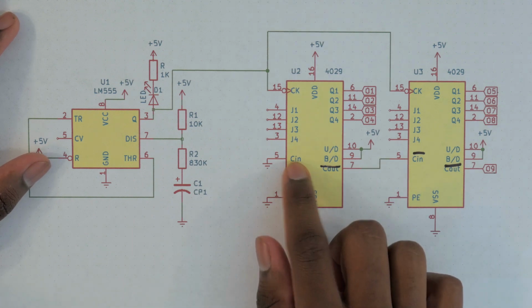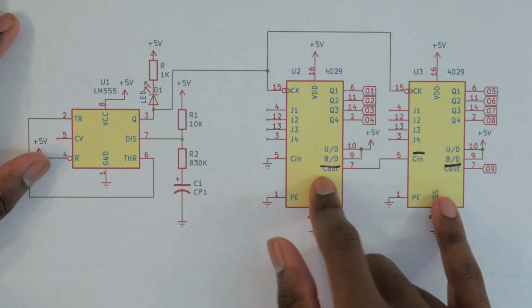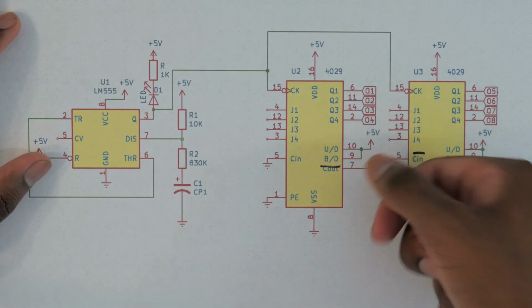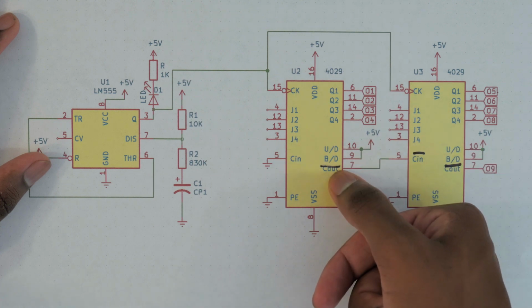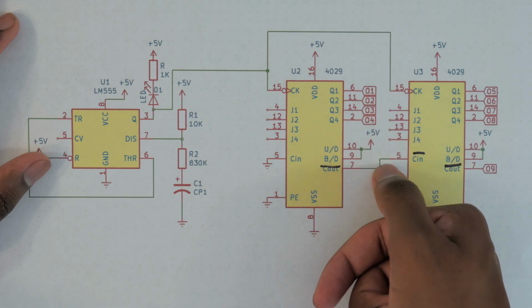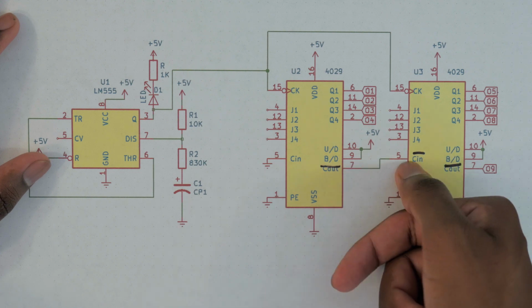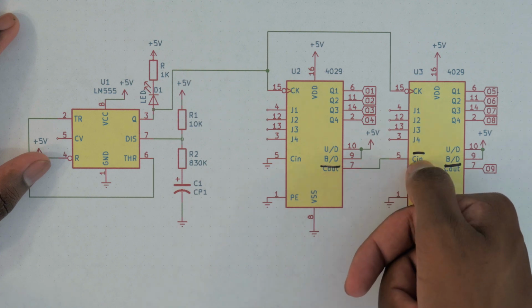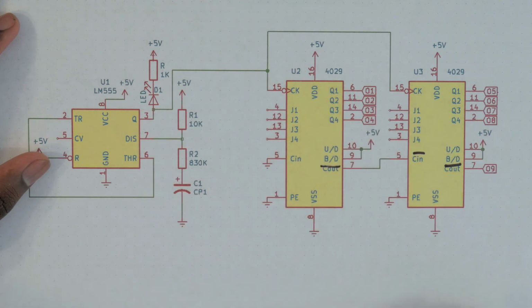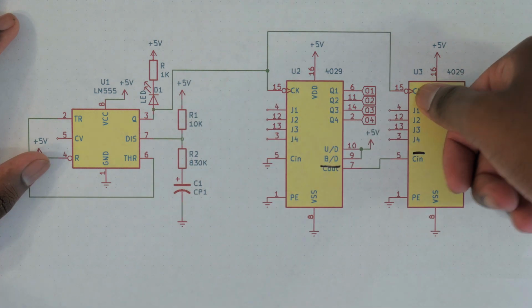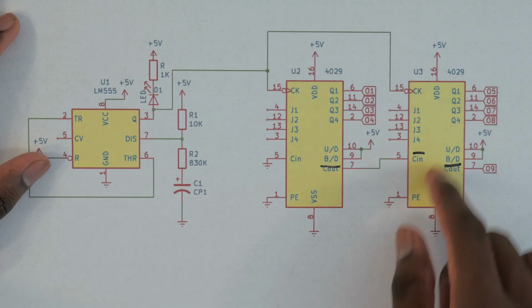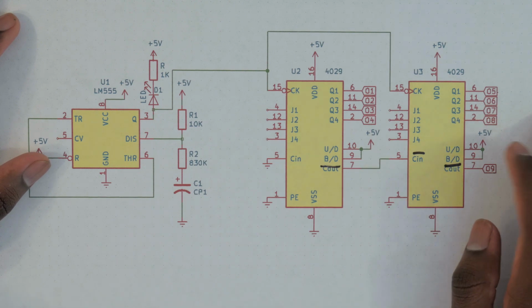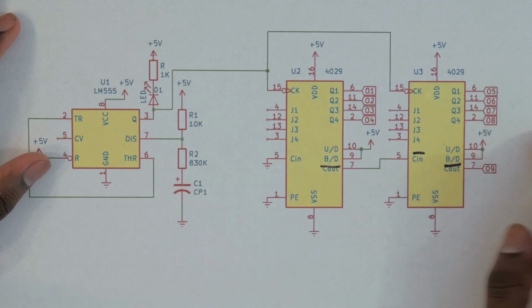Now these pins, the carry in and carry out for these chips, are actually inverted, meaning that a high on the carry out corresponds to a 0 of value, and a low on the carry out corresponds to a 1 in value. But it doesn't really matter because it's going to get re-inverted when we tie the carry out to the carry in of the next chip, and that's how we cascade these 2 chips together. And then the clock signals are tied together, and we do the same sort of preset enable is automatically set to not being used, and binary functionality, and so on.